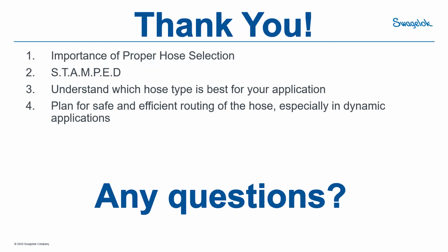Why are convoluted metal core hoses considered less clean than smooth core PTFE? Yeah, they can be cleaned to the same level. What happens with a convoluted metal core, of course, is that the convolutions can trap material, and therefore it's not as drainable, maybe is a better word to use than cleanable or clean. They can be just as clean, if not cleaner, than a PTFE core hose, but they're not nearly as drainable, and I hope that makes sense.